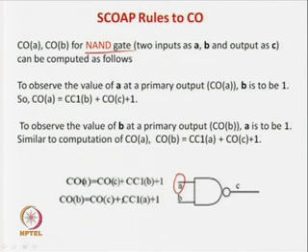If you have to observe this as A, we know that we have to apply a 1, because if you apply a 0 over here, it is non-controllable and everything will be 1, and your whole purpose of test pattern generation is lost. So, you have to apply a 1. So, it is combinational controllability of B to 1, and A is observed via C.